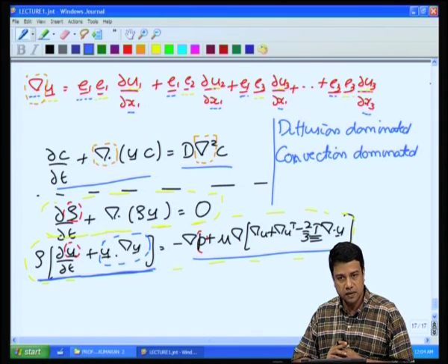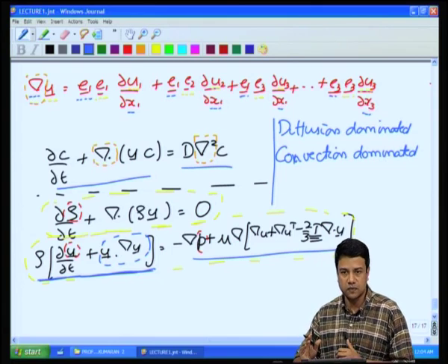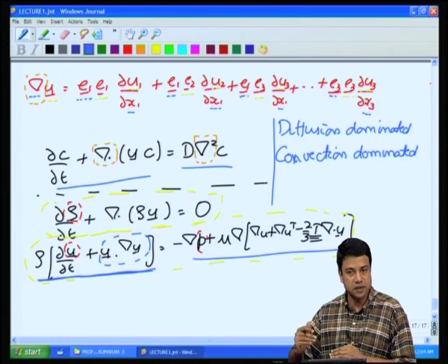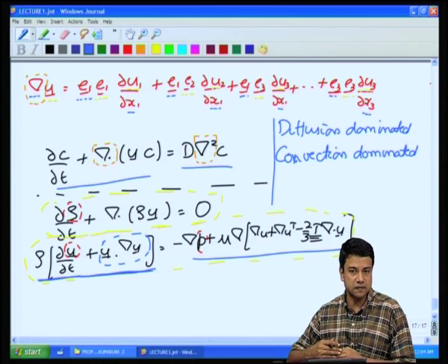Even when convection is dominating, convection can only transport concentration along the flow, whereas for transport of mass or momentum to a surface, at the surface itself there is no velocity perpendicular to the flow. So, you cannot have convection acting at the surface itself. Transport at the surface has to take place due to molecular diffusion.